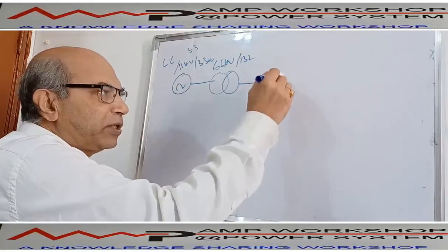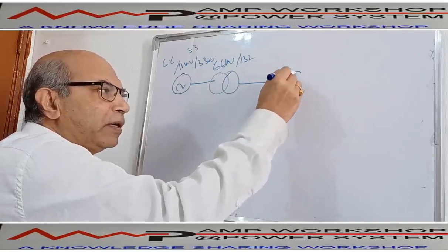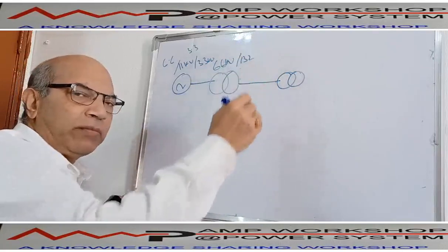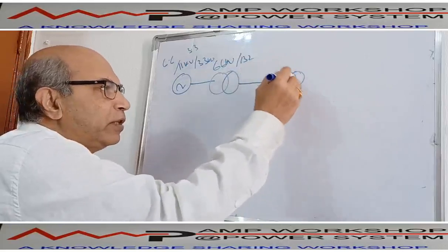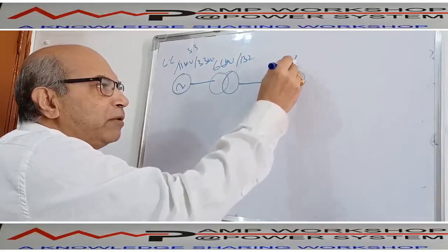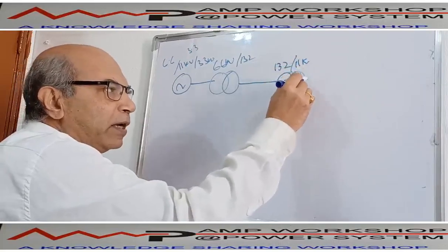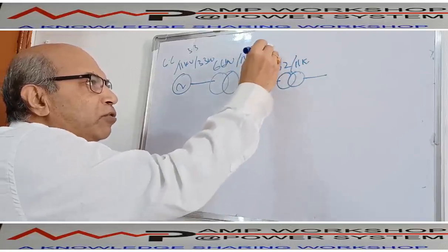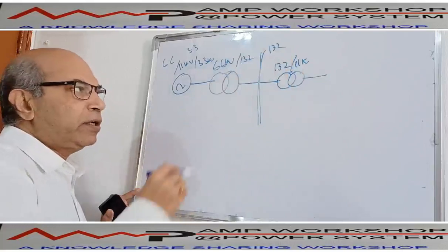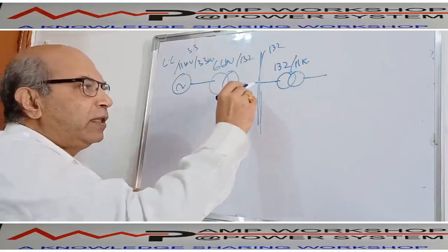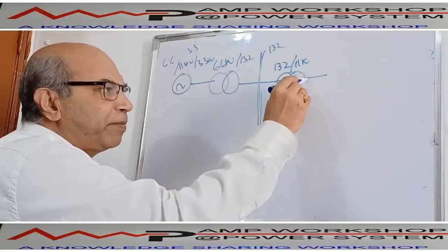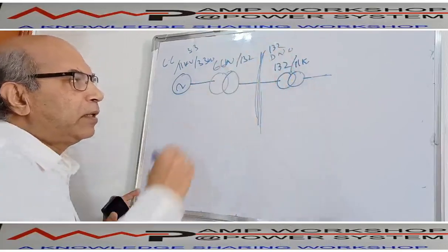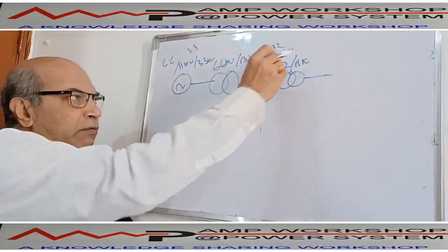At the remote end there is a substation where they receive this power through a step down transformer, or they receive the power at the same 132 kV and then put in a separate distribution transformer. So there will be a step down transformer, 132 kV to maybe 11 kV. Suppose this is one way, and there is another way, a 132 kV switchyard at the remote end. After receiving the power at 132 kV, they go for a separate distribution transformer, 132 kV by 11 kV, maybe from this distribution company, or DNO, which is a network operator.